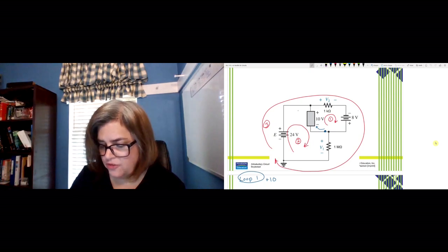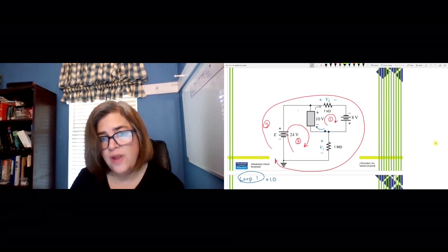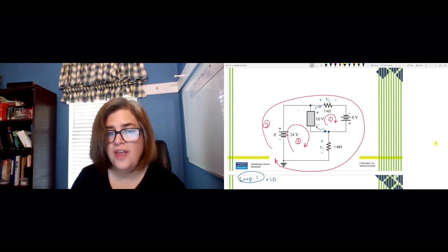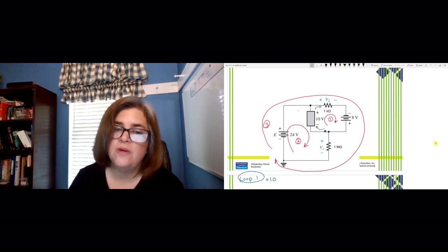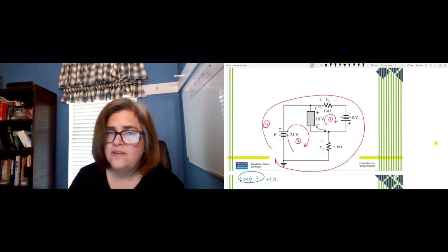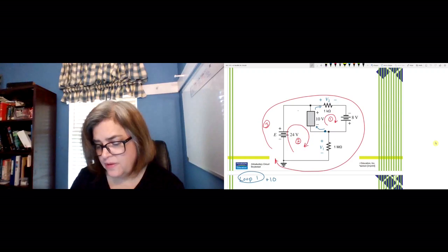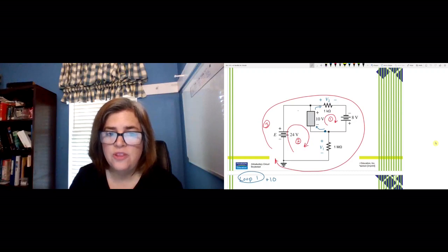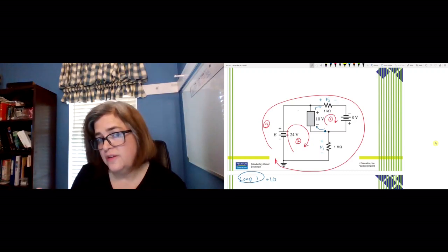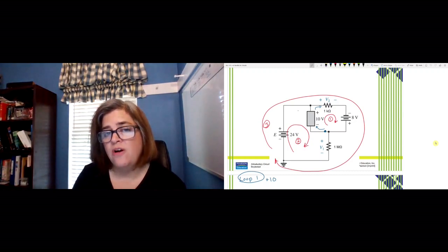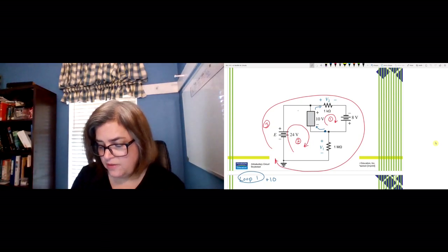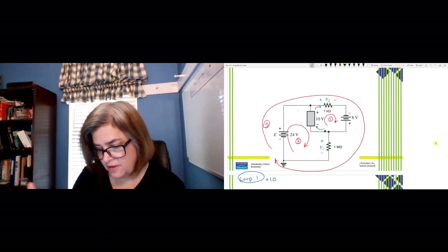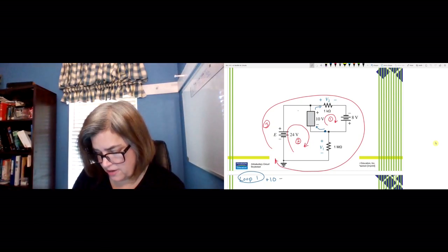And then when we get to our next voltage to consider, we have a drop across the 1 k ohm resistor. Well, actually we don't know it's a drop. We're assuming it's a drop. We drew in the plus and the minus. It's a guess. It may be wrong. We'll see. But because we're going from plus to minus in that clockwise direction, I'm going to subtract V2.